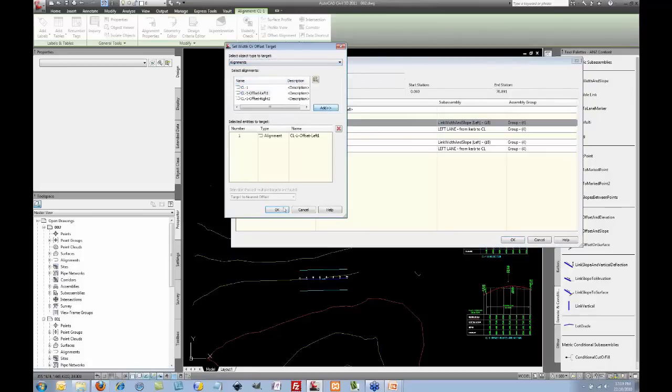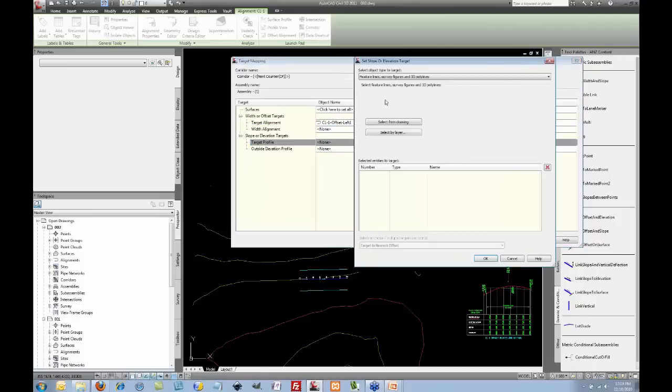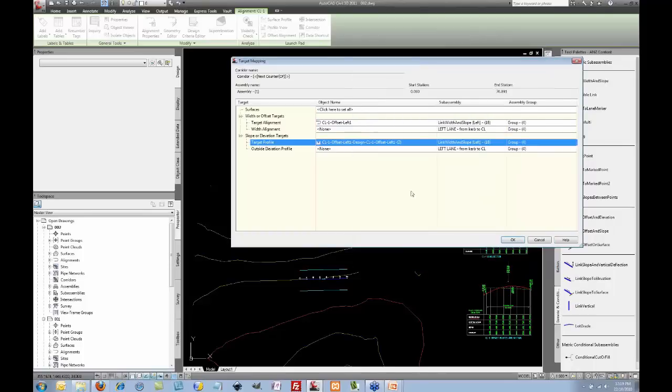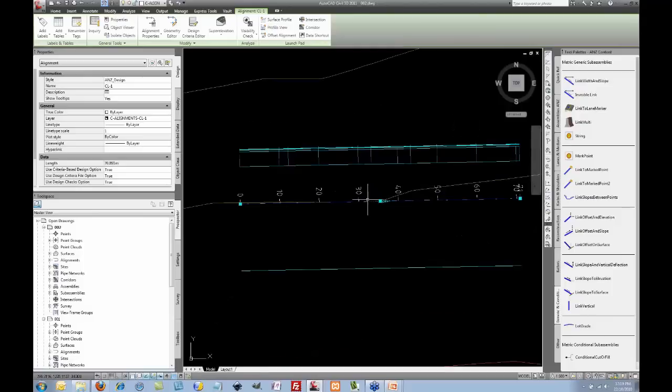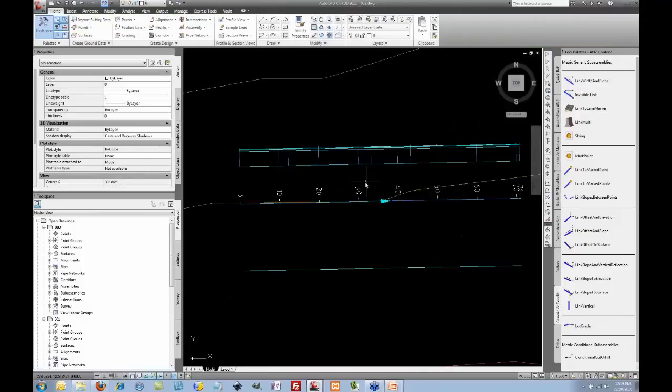So what I'm effectively doing is offsetting to the left, then offsetting back to the right. So what I've done here, I'll actually pause at this when I've completed this one, and I'll show you exactly what's happened. So what I've done here is I have told the software I am adding my corridor model to the centerline string, which is the one you can see the changes on, but I've told it to snap to the edge of the road for my curb and gutter.